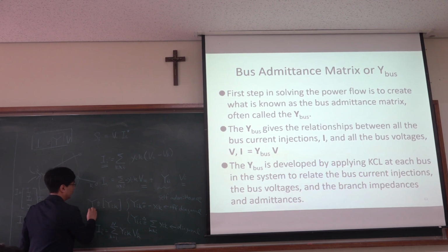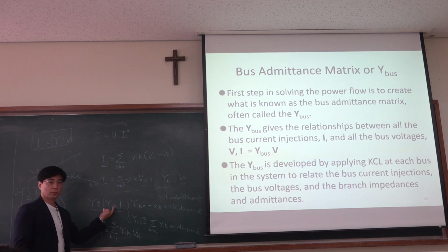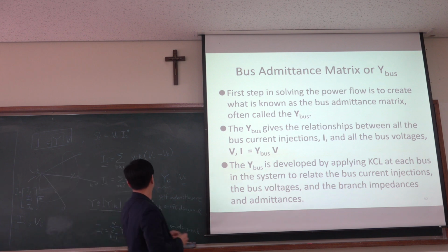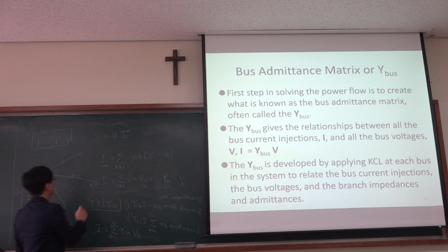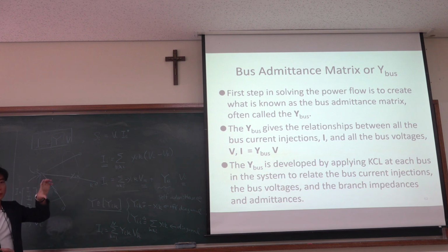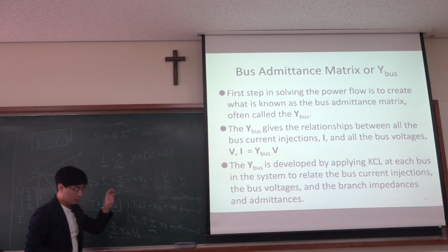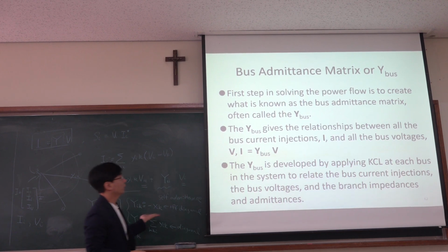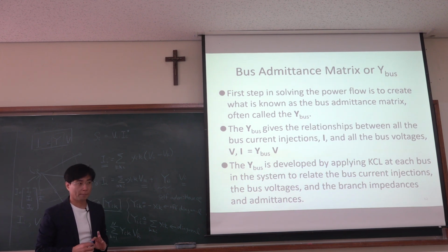Yeah, the notation, this means that this is a matrix and its i's row and k's column element is this one. Okay, so actually in your textbook and in this slide, they are using somewhat confusing notation because to denote the line admittance, they also use the capital Y. So please don't be confused whether that is the admittance of the line or the off diagonal element of the bus admittance matrix, Y bus.